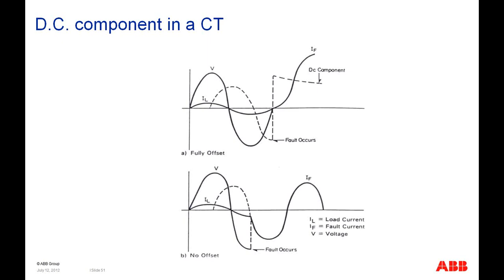There's also a DC component in the CT, because of what happens on the system. Whenever we have system voltage and current in a normal system, and then a fault occurs, all of a sudden we have to put a mimic DC level into the system in order to accommodate that change. Now we have a DC trap component in our current transformer, and that trap component will have to die out eventually, and so the time to saturation is even faster.